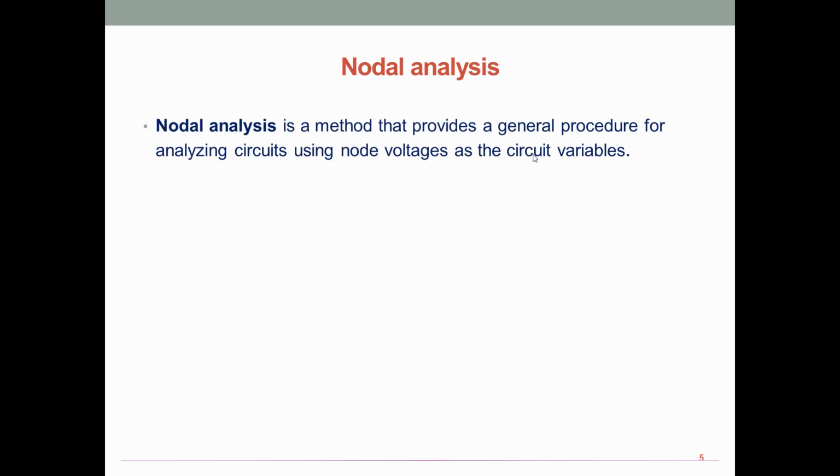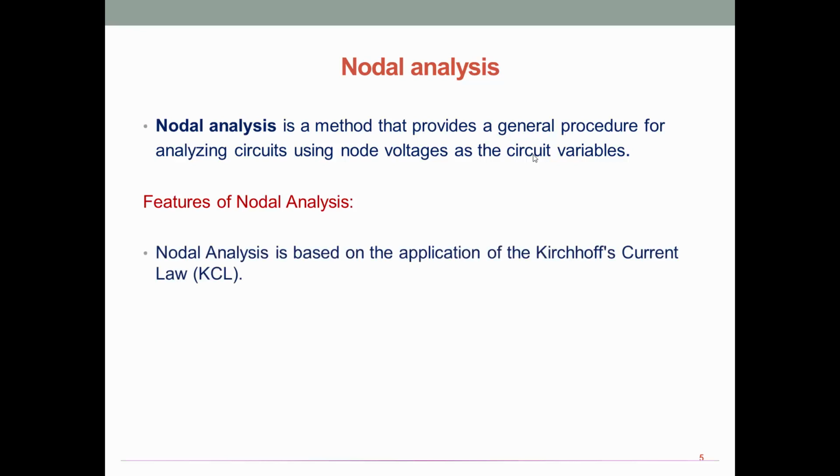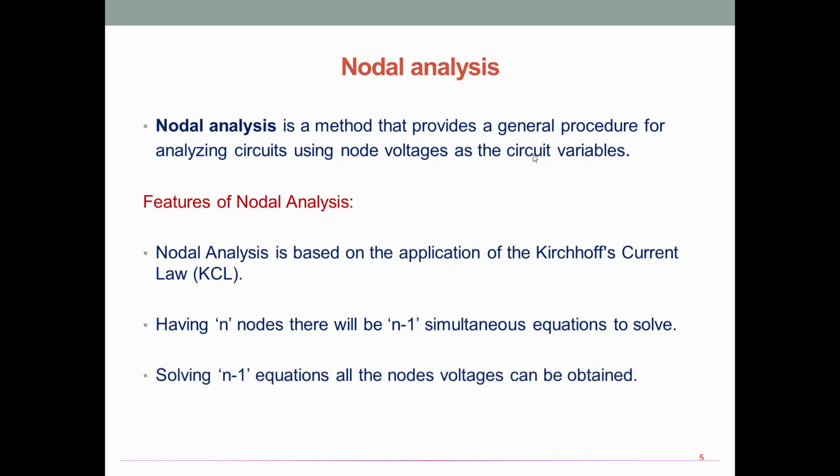What is nodal analysis? It is one of the generalized procedures to find out node voltages, thereby the response at any point of the circuit. What are the features of nodal analysis? Nodal analysis is based on the application of KCL. If you have n number of nodes, there will be n minus 1 number of equations to be solved. Solving n minus 1 equations, all the node voltages can be obtained, thereby any response on the circuit is concluded.